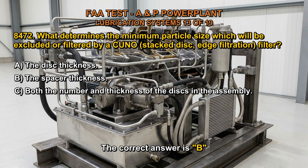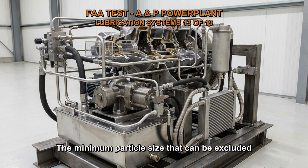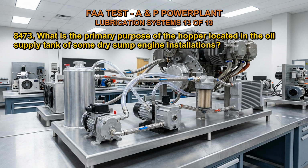The correct answer is B. In a CUNO filter, the stacked discs create a series of narrow gaps through which the oil flows, trapping and filtering out particles. The minimum particle size that can be excluded or filtered depends on the thickness of the spacer used between the discs. The smaller the spacer thickness, the smaller the particles that can be effectively filtered by the CUNO filter.